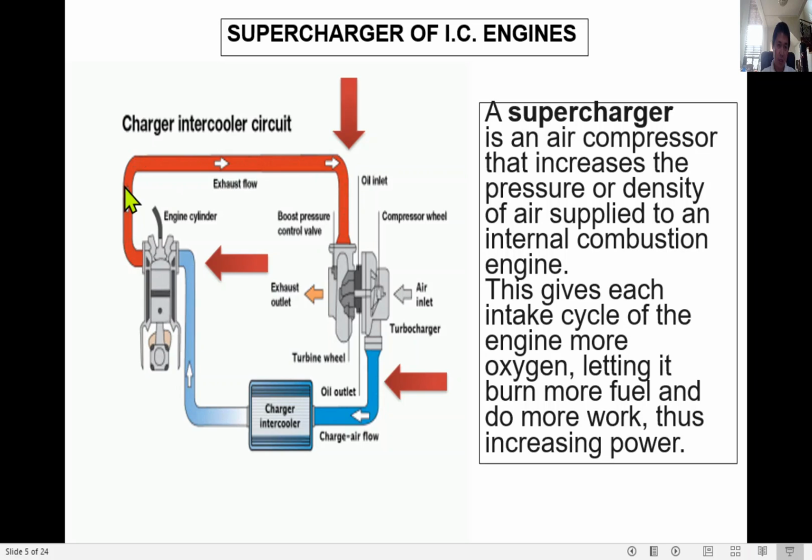It's flowing to the exhaust outlet, to the exhaust manifold, and entering the turbocharger turbine side, the turbine wheel. So this is the turbine inlet. The exhaust gas of the engine pushes the turbine wheel of the turbocharger so that the turbocharger spins, rotating at very fast speed. See?